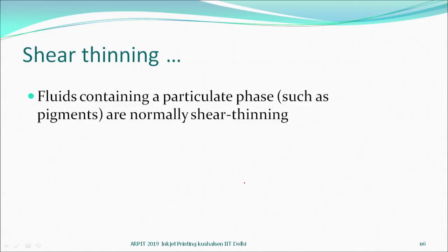Shear thinning is a property. When you apply shear, the viscosity goes down, which is basically a good idea. It is needed because you do not want to increase pressure. It is always better that when you apply shear, the fluid easily comes out of the nozzle and later on can have the same viscosity as required. So, shear thinning is that property which obviously would be needed.